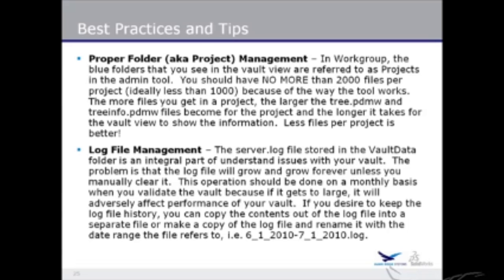It's basically just a text file. You can open it up in Notepad and you can delete everything that's in it. And you should do that once a month when you're doing your vault validation. That way the server log file is always the optimal size. It's never going to get too large.